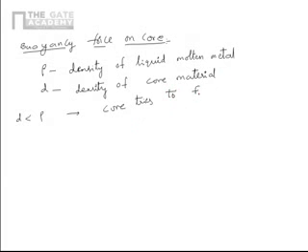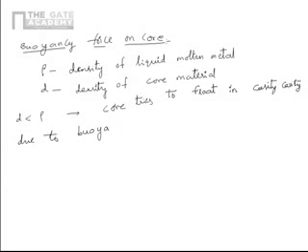Similarly here, the density of the molten metal is higher than the density of the sand, so the core tries to float in the casting cavity due to the buoyancy force. Buoyancy force is nothing but uplifting force.